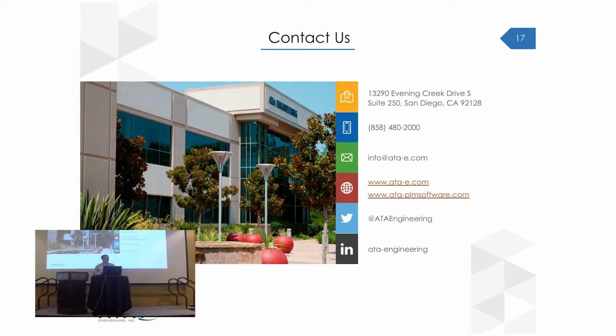Is it capable of determining, or inputting, whether you want to change the stiffeners from, say, a plate and a flange, or a T, versus a beam element? Yes and no. Currently, based on feedback from the folks we were working with, their process was to shell mesh all stiffeners. So if there was an angle, they would shell mesh both parts, or if they were T's, they would shell mesh both.